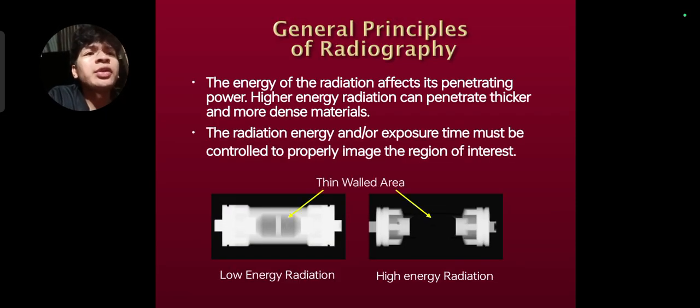The general principle of radiography is that the radiation energy affects its penetrating power. Higher energy radiation can penetrate thicker and denser materials. As you can see in the image, we can easily differentiate low and high radiation energy. The left one is the low energy radiation image, and the right one is the high energy radiation image, in terms of a thin walled area.